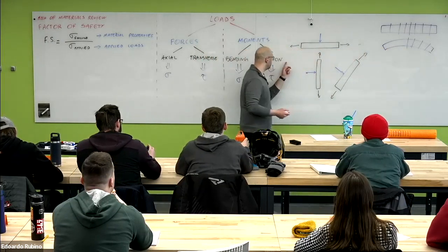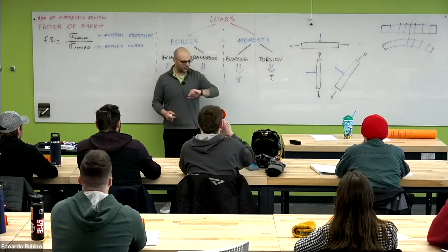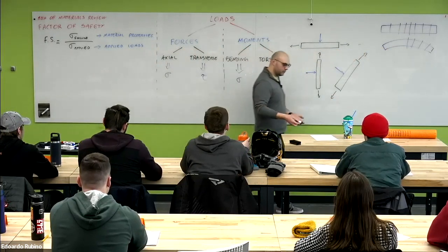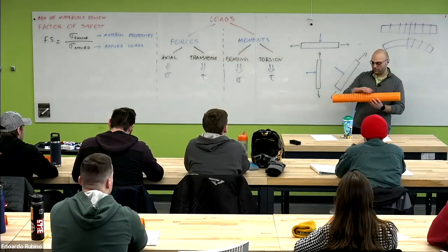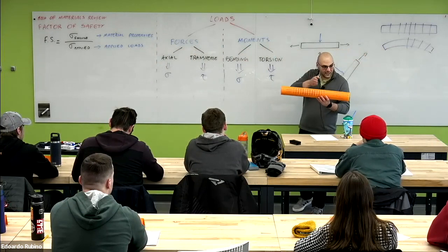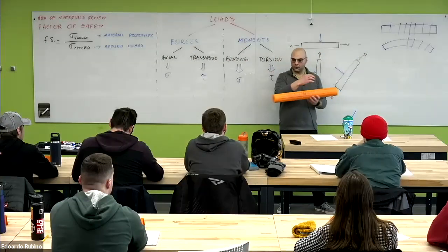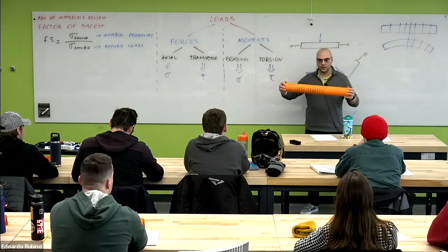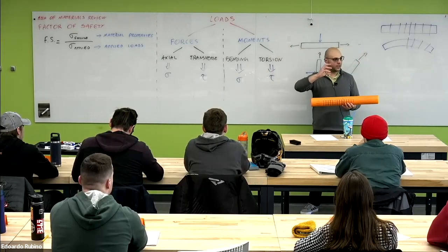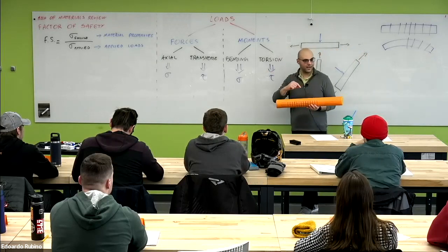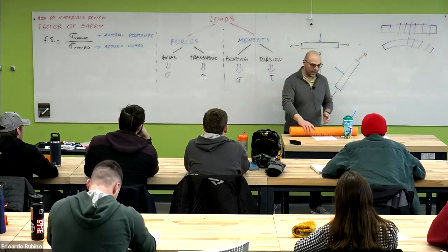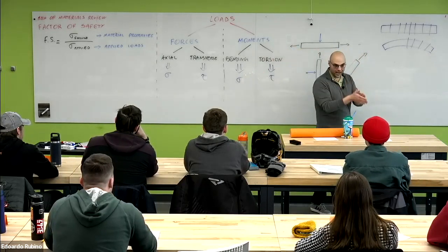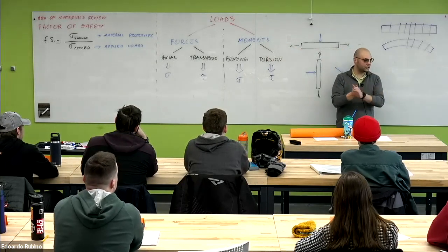On the other hand, when we model a beam that is subjected to a certain torsional load, we imagine that our beam is made out of a lot of discs, one against each other. When we have that twisting load, each disc will rotate slightly with respect to the next one. And all these relative rotations are basically shear strains, which means that we have shear stress.